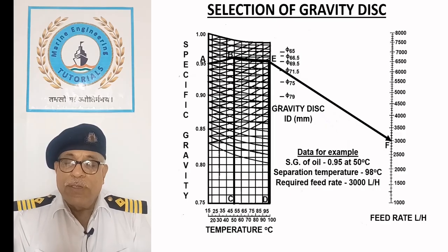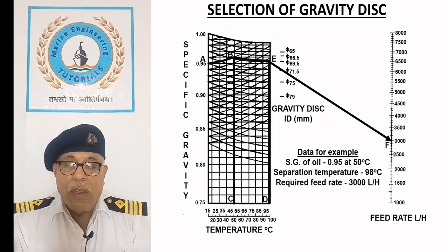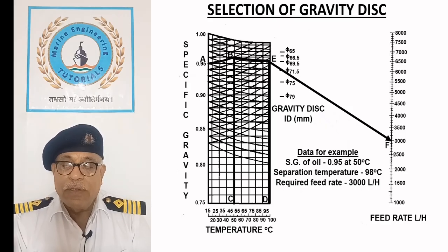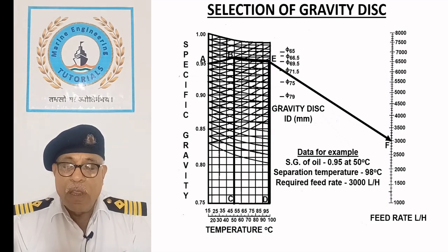Conversely, reducing the specific gravity of oil will shift the interface inward towards the axis. This reduces the centrifugal force acting on the mixture, lowering separation efficiency and potentially allowing contaminants and water to carry over with the light phase outlet.